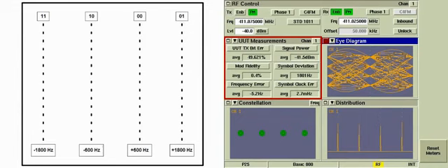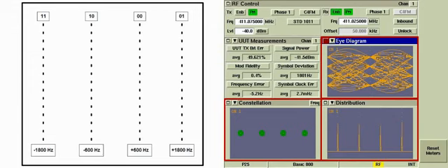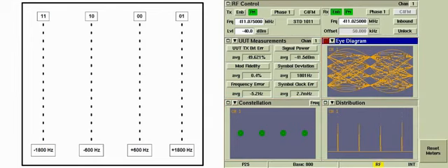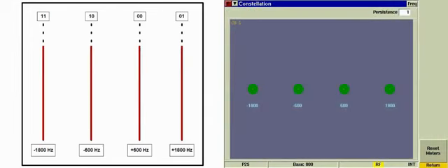The UUT measurements tile displays the numerical results of the modulation fidelity measurements. In addition to the numerical displays, the instrument provides 3 graphical displays that provide a visual dimension to these measurements. The constellation display provides 4 green circles for identifying the ideal locations for each of the measured deviations. A perfect signal would show a single dot in the center of each circle, though in reality there is usually a line that shows the spread of deviation for each symbol.